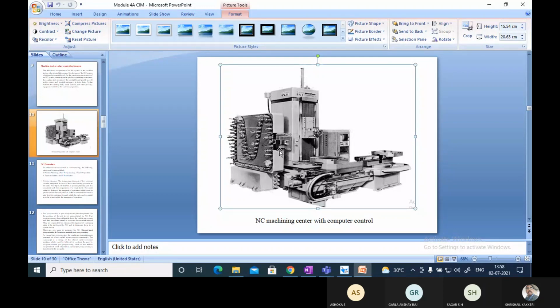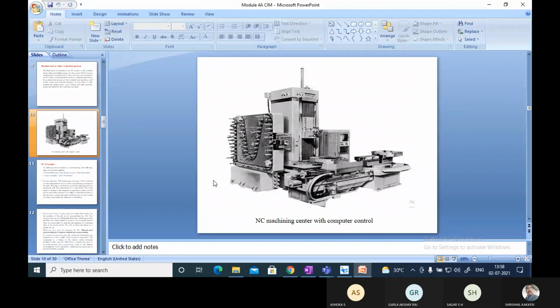the machine itself. So for example, if I want a 10 mm diameter cutter tool or a 10 mm diameter drilling tool, that will be located at a particular location in this station. This is called the workstation, and this is called the tool station. While the programmer is giving the instructions to the machine, it is his responsibility to give which tool has to be selected for what machining. So that will be given by the programmer himself.